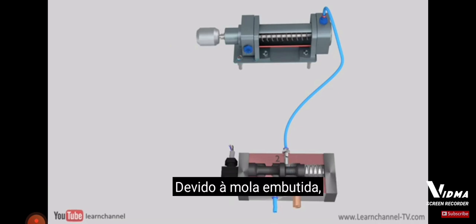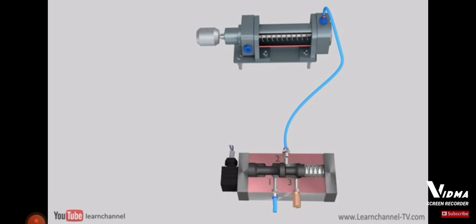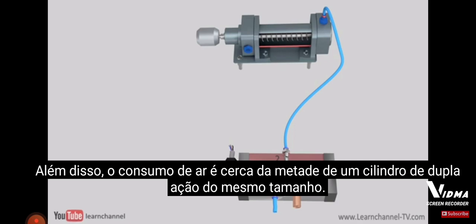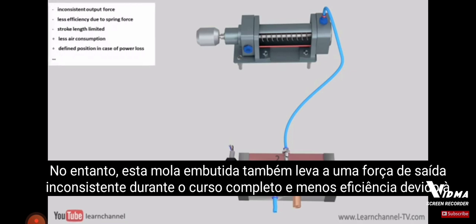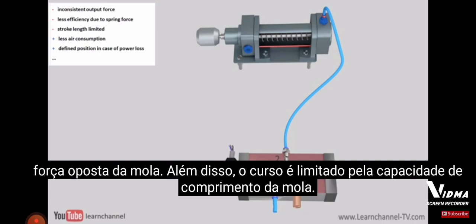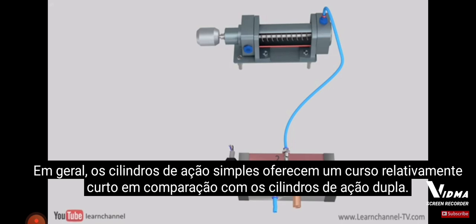Due to the inbuilt spring, the piston returns to its base position in case of a power loss. Besides this, the air consumption is about half of a double-acting cylinder of the same size. However, this inbuilt spring leads also to an inconsistent output force through the full stroke and less efficiency due to the opposing spring force. In addition, the stroke is limited by the spring length. In general, single-acting cylinders offer a relatively short stroke compared to double-acting cylinders.